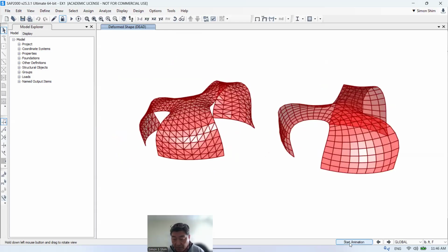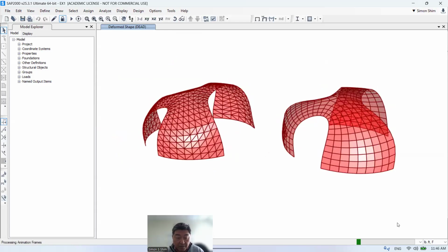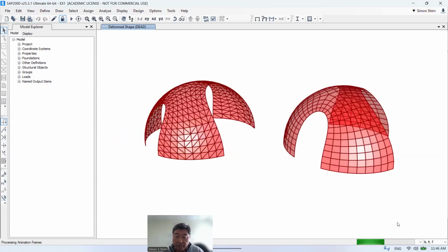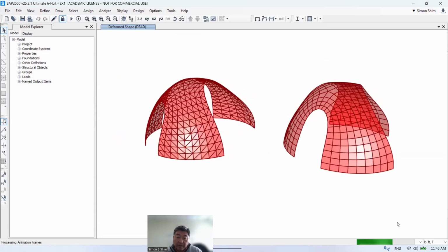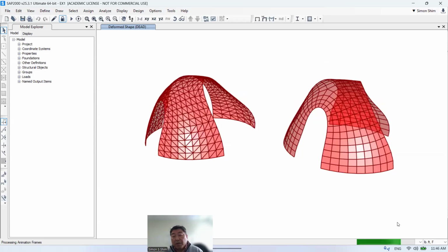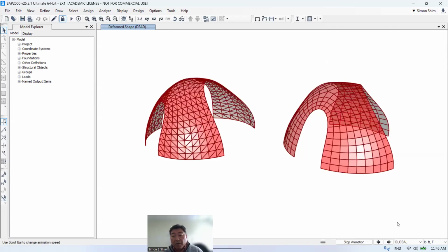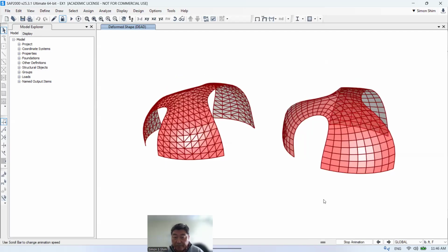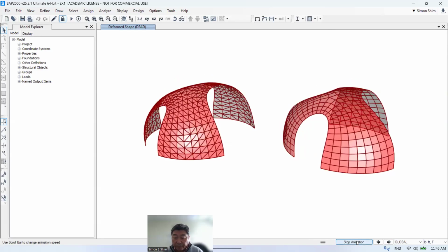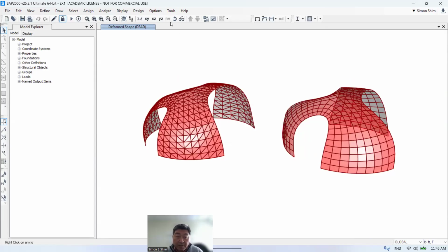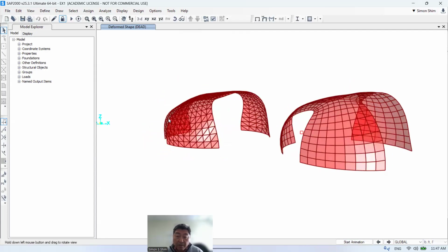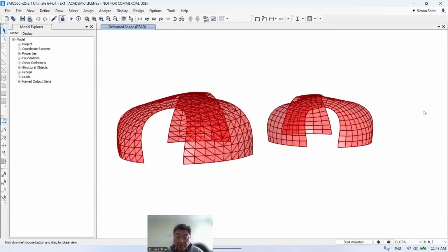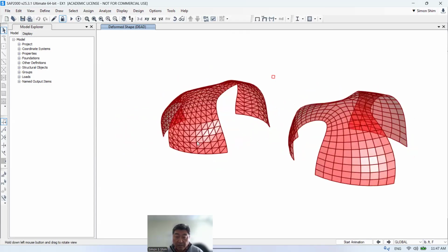Here, if you want, click start animation. So you can always cross-check your models. Everything is connected and properly showing your expected building behavior based upon self-weight. Seems like it makes sense, right? Is the building structure deformed like this, vertically?